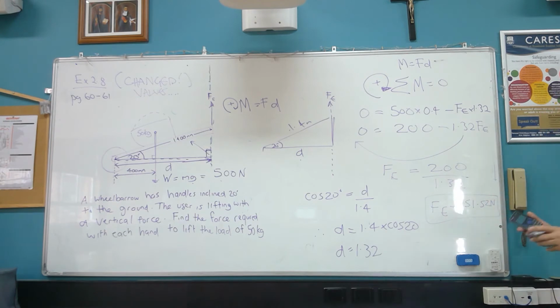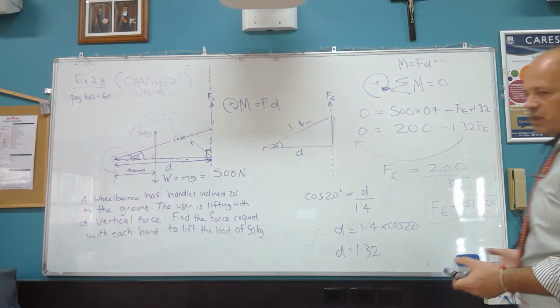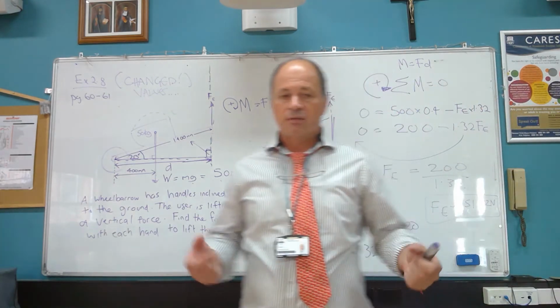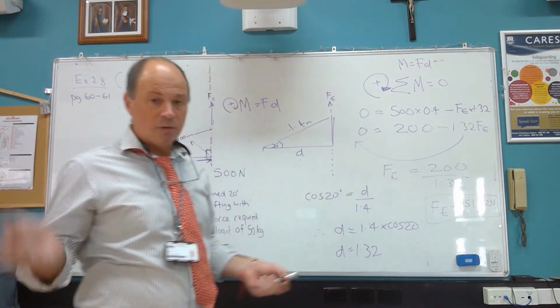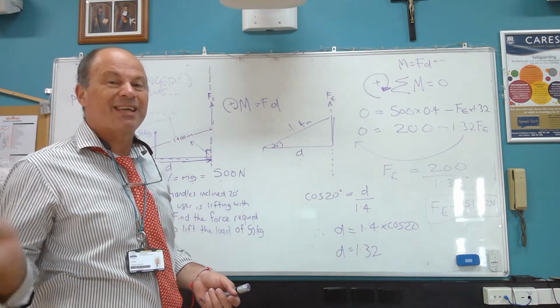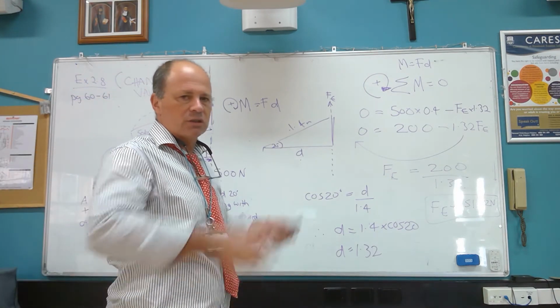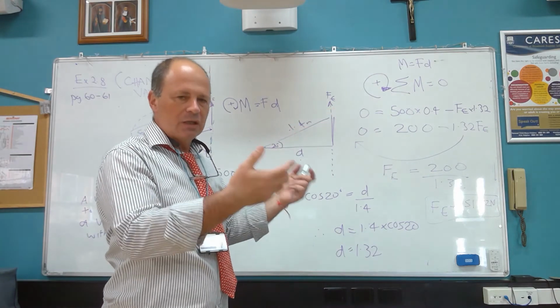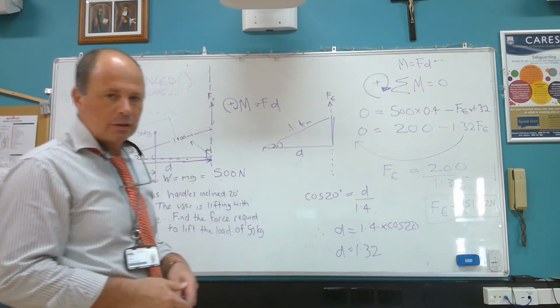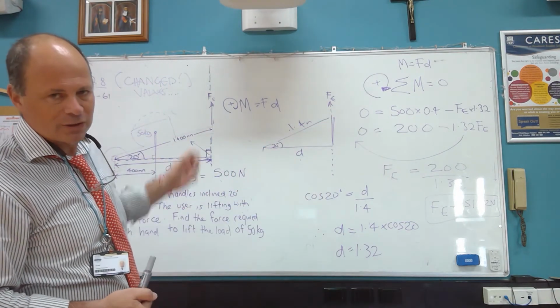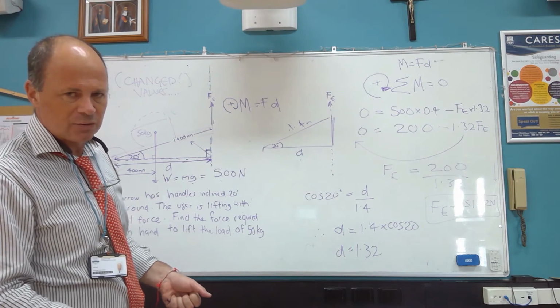That's our force of effort. So we've introduced a new concept here, the concept of equilibrium. Now when we do truss analysis, if something's not turning and it has a moment applied, it's because there's another moment cancelling it. Okay, so if you don't cancel that moment, the thing will just keep turning. So if we have an equilibrium situation, it's always going to be a stationary situation.